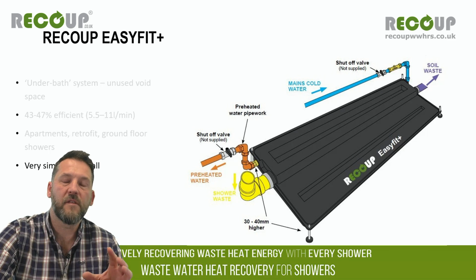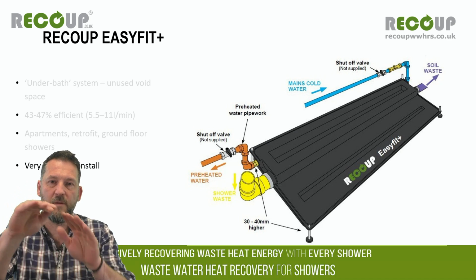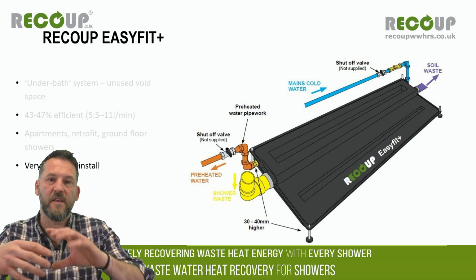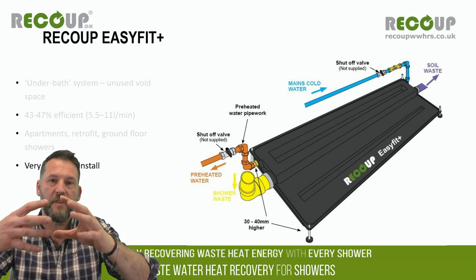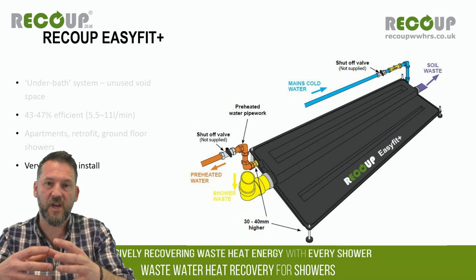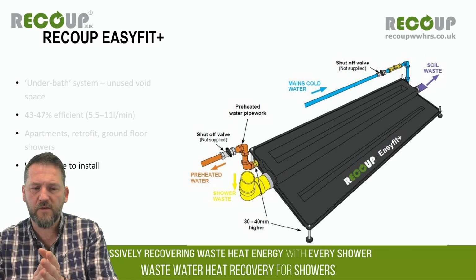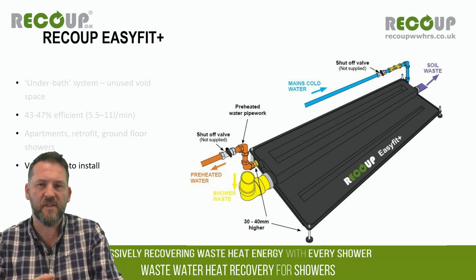What happens here is the heat exchanger is designed to be around about 2 millimeters above the base of the wastewater heat recovery pan. So as that warm waste goes into the unit and floods out, at the standard shower flow rates, there's enough waste flow there that it will roll over, turbulate and mix over the exchanger, giving lots of mixing and lots of surface contact and lots of heat exchange. So this product scores very well in terms of efficiency, and certainly I think the next closest product in production on the SAP database, it's around about 40% more efficient than that.